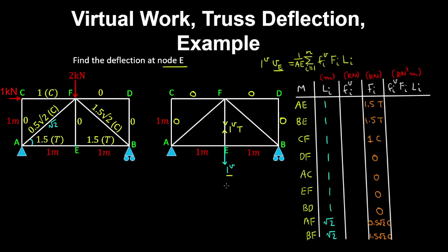And we write this as a tension member just for convention, noting that the virtual load does not cause any deformations of the truss. And by symmetry you can find the reactions of the truss, so that will be equal to half the unit load of 0.5. And I'll leave it for you to take equilibrium of the other joints using the method of joints, and you'll be able to find the forces in the other members.